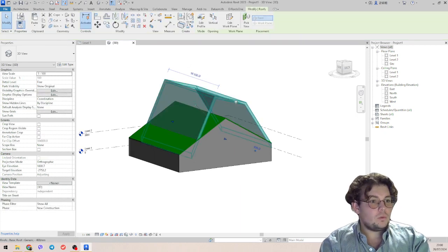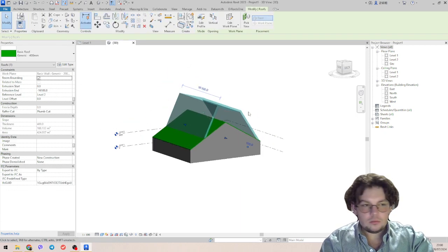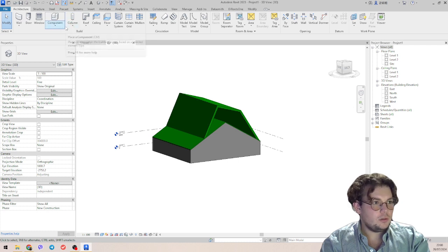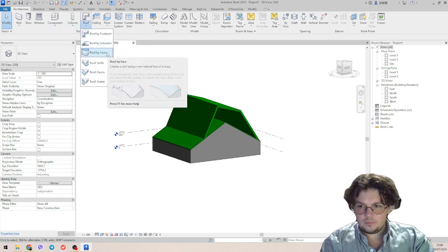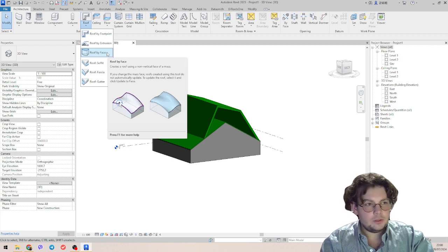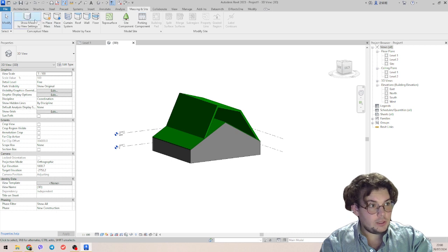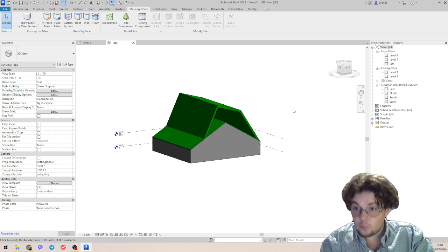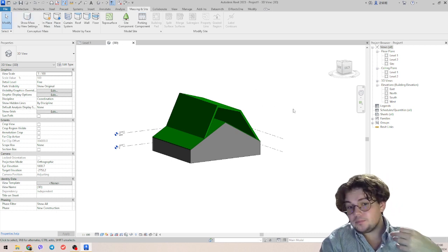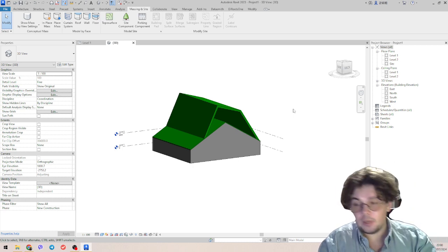So mostly the idea is the same, just the roof by extrusion, and actually roof by face. With this one you can actually create, there is in this parameter massing inside, you can create different forms, really adjustable ones and really parametric ones.